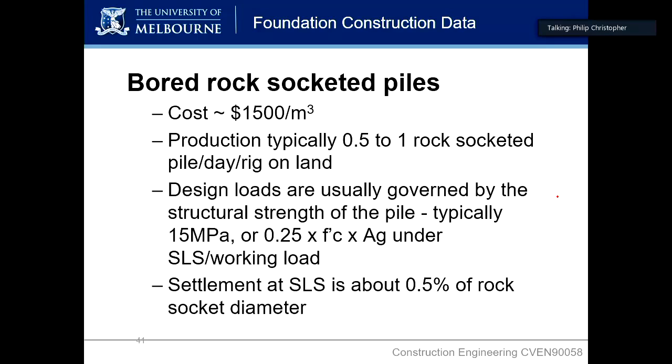What was the geology there for Parkville? Does anyone know? Yeah, Melbourne Formation. So we've got a lot of rock. Not super strong rock, but if you're drilling, what were they drilling, 30, 40 metres into this rock in various locations, a CFA rig's not drilling that far into rock. It's just ludicrous. So we have to have a bored pile as soon as we're drilling into that stronger material for a reasonable depth. So design loads are typically governed by the structural strength of the pile.